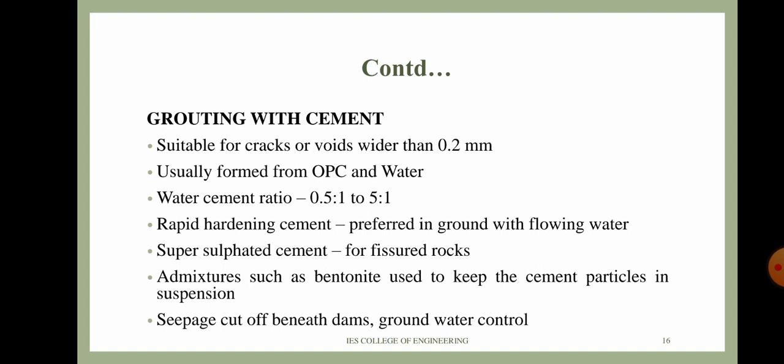Supersulfated cement is used for fissured rocks. Admixtures such as bentonite can be used to keep the cement particles in suspension. This grouting with cement is applicable in the case of seepage cutoff beneath dams and in case of groundwater control.